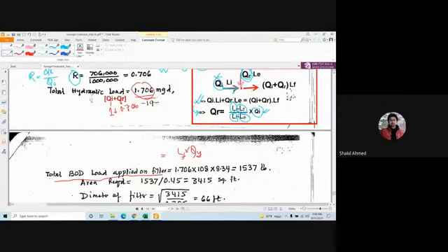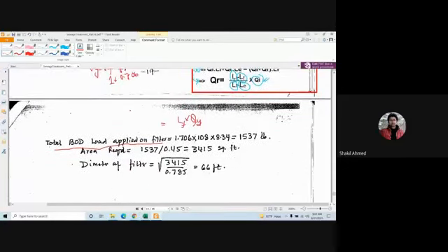And QY equals what? QI plus QR. That is 1.706. So this is 1.706 and LF equals 108 milligram per liter. And you need to have a conversion factor 8.34. Okay, so this will be pound. Basically, this is pound per day. Clear?